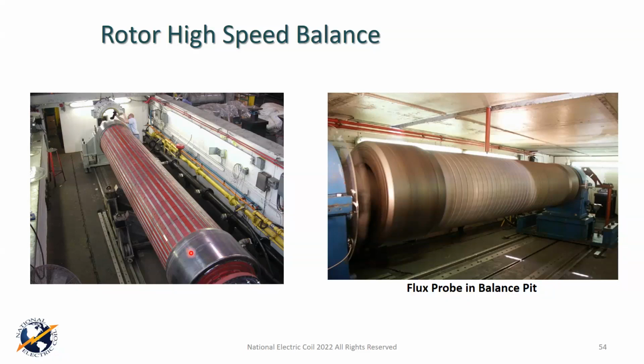Before you put that rotor in the pit, you did a complete set of total indicated runouts, or TIRs. And you're going to do another set of TIRs as soon as you hit overspeed and hold it for a minute. So you're going to be able to tell if the rings have moved adversely or if they're seated in an unusual position. And the TIRs that you're producing the second time as compared to the first time are going to help indicate that to you.